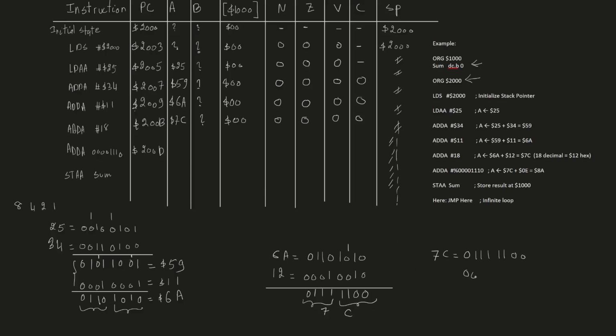And then this binary number, let's add it as it is. So 0000 1110. So if we add them, we have 0, 1, 0 with carry 1, 1 with carry 1, 0 with carry 1, 0 with carry 1 again, 0 with carry 1, and then 1. So this one in hexadecimal will be 8. And then for these 4 bits we have 8 plus 2, 10. 10 is A. So the accumulator A will have a value 8A in hexadecimal.